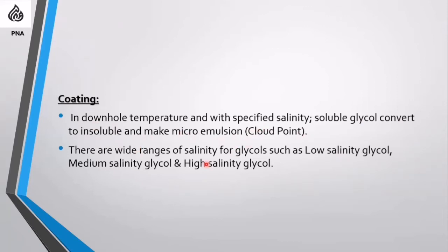So the glycol will convert from soluble to insoluble when it finds a specified salinity, which depends on the type of glycol and the temperature.